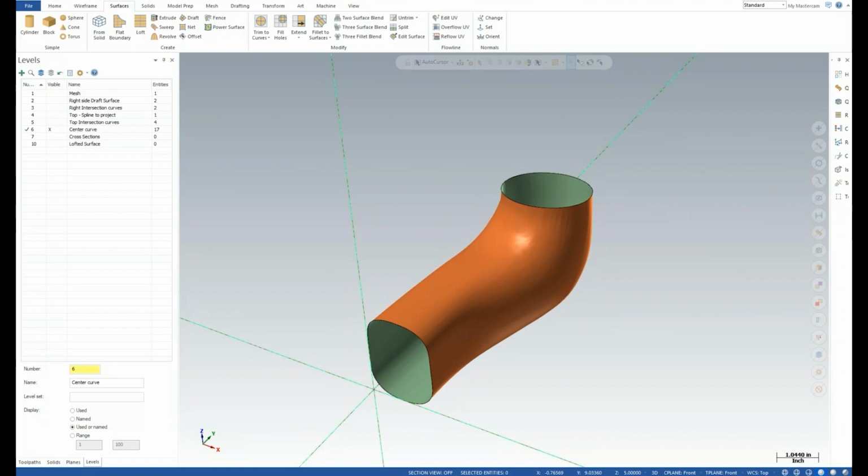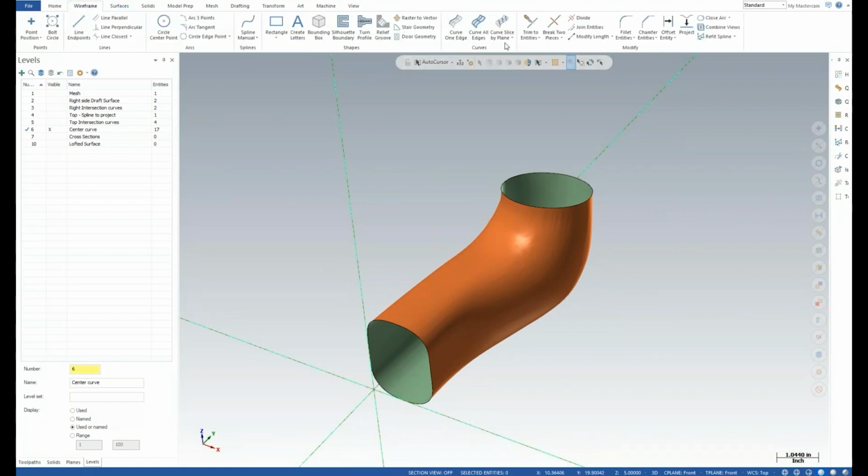A lot of the mesh functionality is in Tech Preview 1, although Tech Preview 2 has the intersection to mesh, and it also has the modify at intersection function. So you find that here. And that's where you could have a bunch of wireframe entities passing through a mesh and find that intersection, whether you want to break or trim or create points or whatever. But there's a lot of good stuff in TP1 and more coming in TP2 and even more after that.